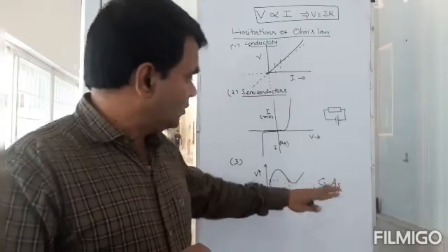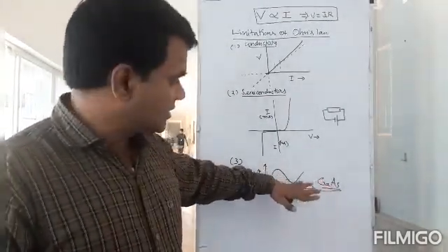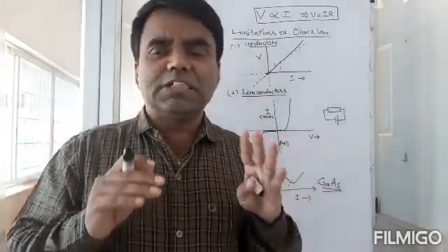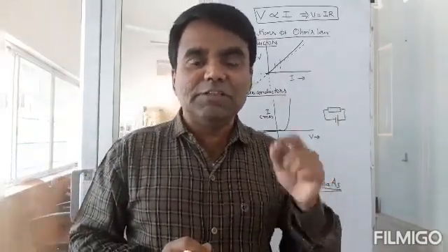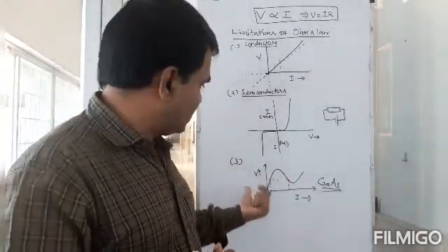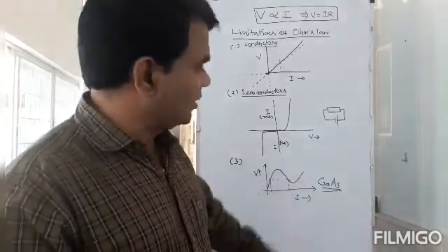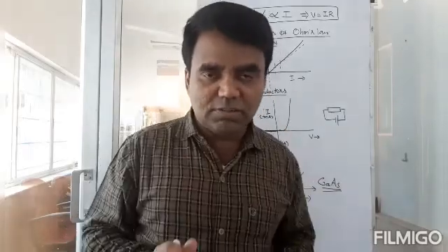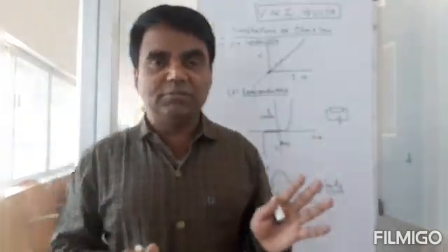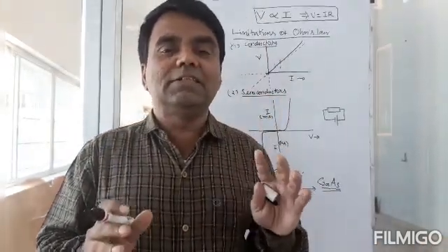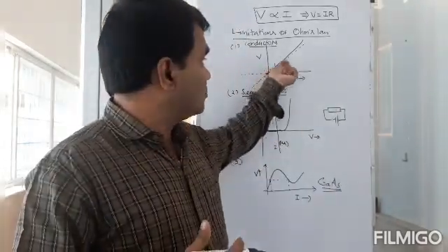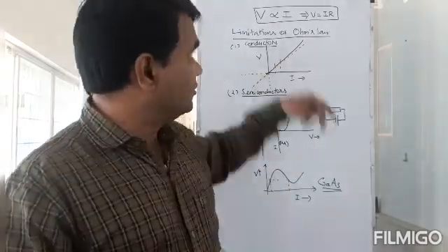Okay, so this is one of the instances where Ohm's law is not obeyed. Even though we say that voltage is proportional to current, which is fairly okay in the case of conductors, Ohm's law is not strictly obeyed. It definitely is not obeyed in the case of semiconductors and special materials like gallium arsenide, where you have a dual thing. Okay. So Ohm's law is a good law. It's a good practical law, and it gets us through a lot of problems. But it is not a complete law. Not all materials obey Ohm's law. Even materials which are supposed to obey Ohm's law, like conductors, don't obey it very strictly. Okay? So these are the limitations of Ohm's law.